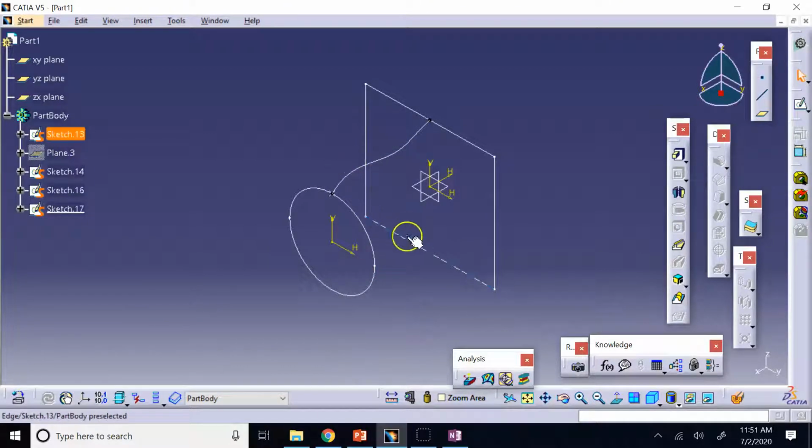Now, let's say I also need a guide at the bottom, right? So this is the top guide. I need a bottom guide. Now, the main point is this. If you want more than one guide, the guides should be on different sketches. In other words, this sketch number 7, which is for top guide, you cannot, in the same sketch, draw the bottom guide. It doesn't take it from you. Different guides should be in different sketches, like different profiles that have to be in different sketches. So you need 4 different sketches here at least.